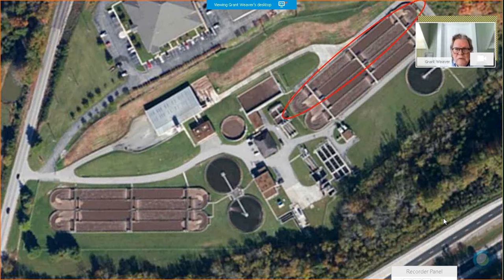So here's how the facility's designed to work. We're going to focus on one of the ditches here. So there's 4 of these ditches, so same story times 4. Each ditch has 6 rotors, horizontal shaft aeration rotors. There's 6 of them in that one ditch. All the other 3 ditches are just the same. So 6 times 4, there's 24 of these rotors designed to run all the time.